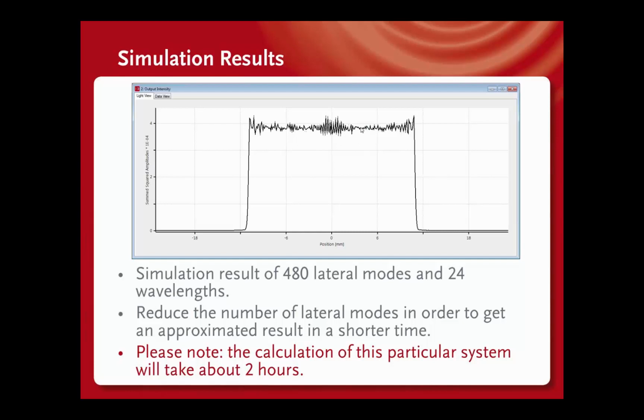If you would like to overcome these effects and have a more homogeneous light pattern, then we have to optimize the lens array pitch and focal length. We can change the focal length of the collimation lens, and we can probably select a different LED with a different chip size.